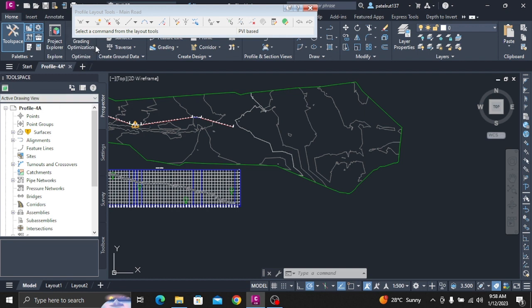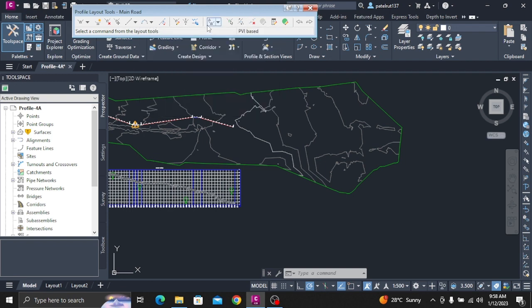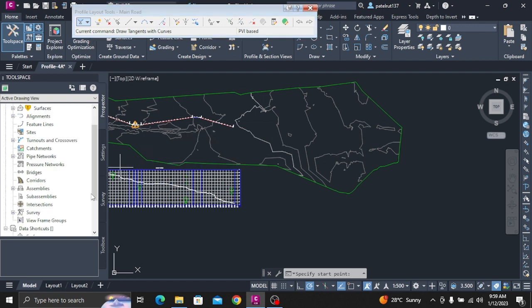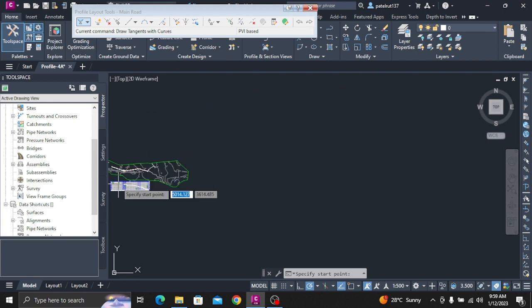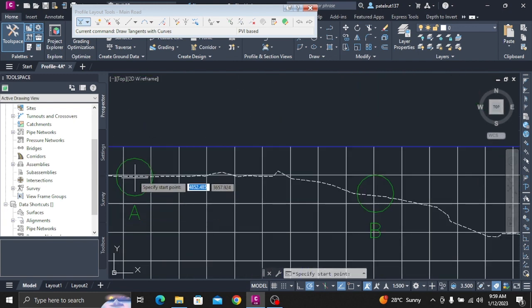Click Next. On the Profile View Height page, specify the following parameters. Profile View Height, User Specified. User Specified, 50.00 foot. Profile View Datum by Mean Elevation. Split Profile View, selected. Click Next. On the Profile Display Options page, ensure that the Draw checkbox is selected for both profiles. In the Oak Road Proposed row, select the Split at option. Click Next to open the Pipe Network display page.